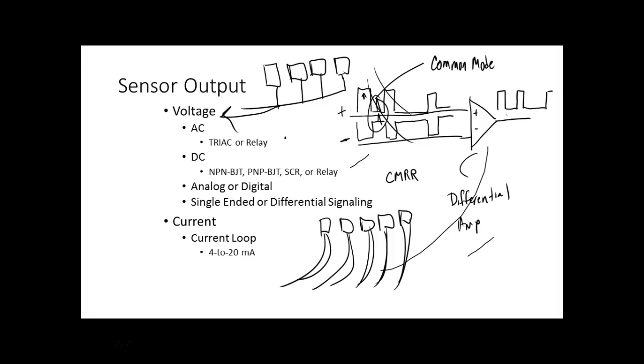And when we're over there in the lab, we'll show y'all the Profibus. In fact, some of y'all probably have seen it, where we've got all the PLCs connected together. And over there on the robot, we'll probably run that thing down and let you see that it's all hooked up. We've got all these guys up on top of that robot, but they all come out of one cable. So we're not running individual wires anymore. We're networking. These guys are networkable now. All our sensors are. So we can buy different interfaces for PLCs where we can handle these networkable sensors. And just about all these use differential signals.